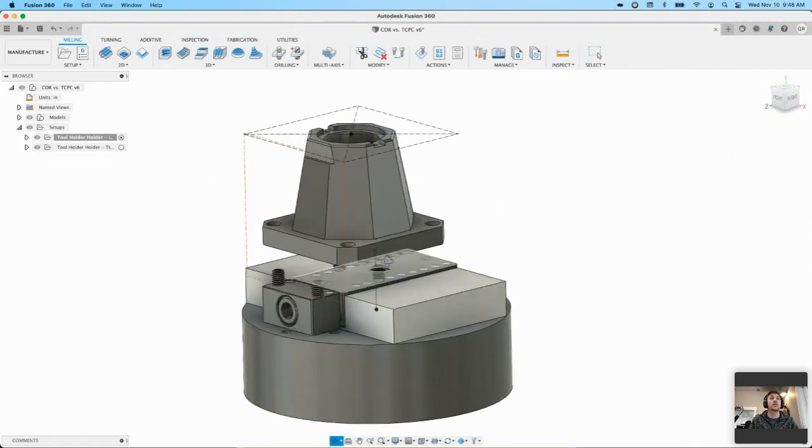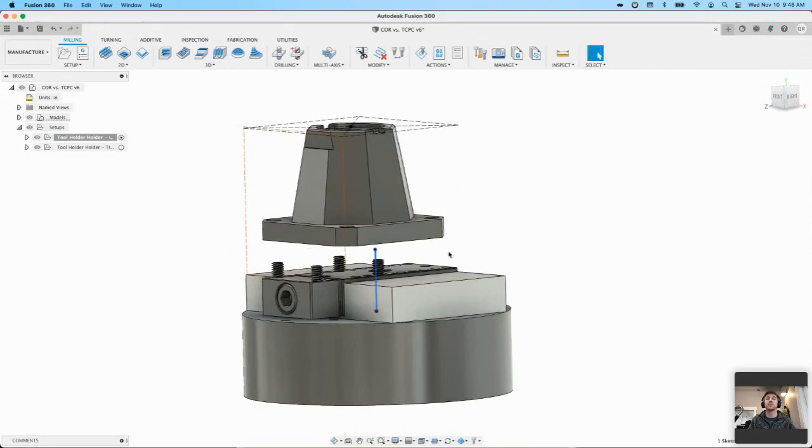On top of that, we had to have a representation for our B table offset. Basically, that's the term we use for that point above the B table that represents the center of rotation. That's different from machine to machine. So users had to have something that represented that, and make sure that this line, or the distance from the surface of our B table to this point, was the right dimension relative to your machine. So that had to be adjusted.